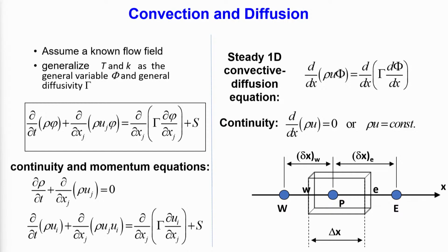So, as usual we have constructed a control volume, the nomenclature is exactly the same as what we used for the diffusion problem. One dimensional version of this means you have only x direction and steady. Unsteady we are not bringing it here, because how to treat the unsteady term, whatever we have discussed for the diffusion type of problem, is the same for all types of problem. That is, you have those explicit, implicit, Crank-Nicolson types of schemes. So, that is not dependent on whether advection is there or not.